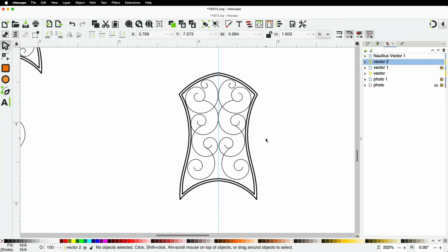It's good for those things, but it's not good for, say, V-carving on a CNC router, or if you're running a laser engraving machine where you need some thickness to the lines. I say that because programs like Lightburn that actually do this type of laser engraving do not respect the stroke width. So you need to create filled shapes for that. And I'll quickly show you how to do that next.